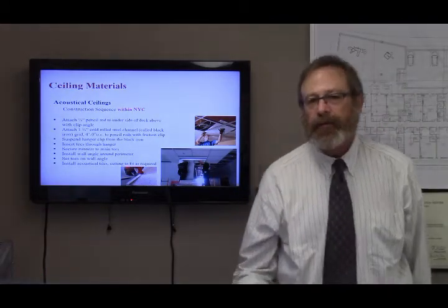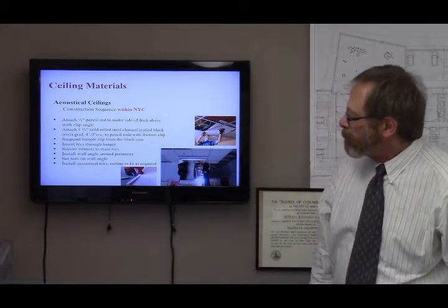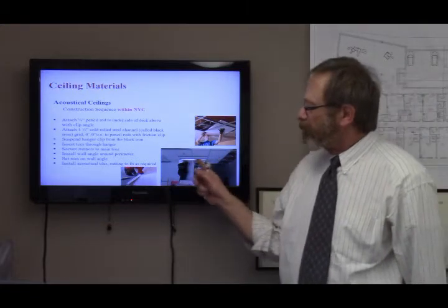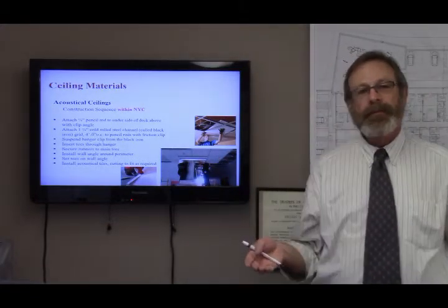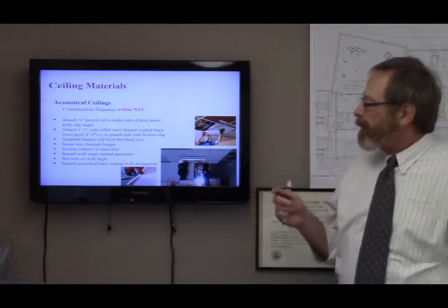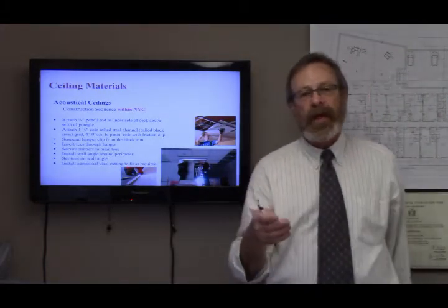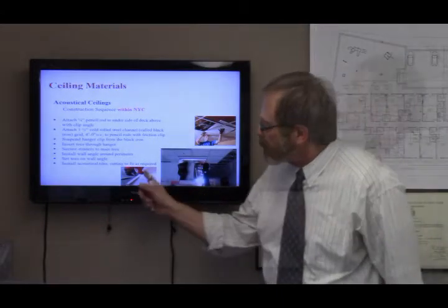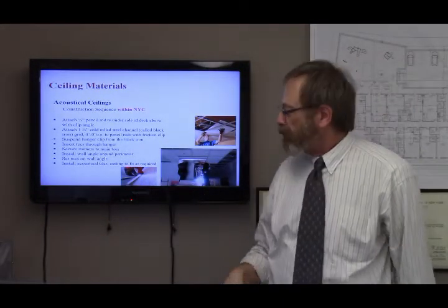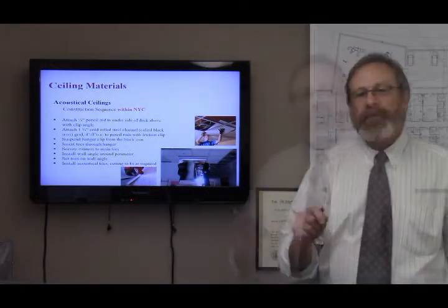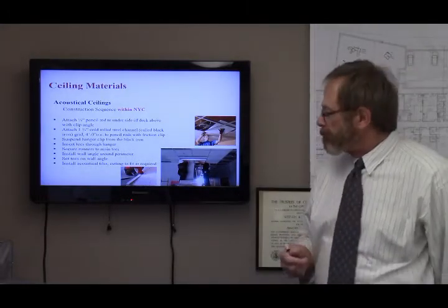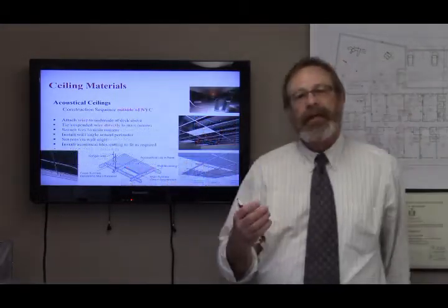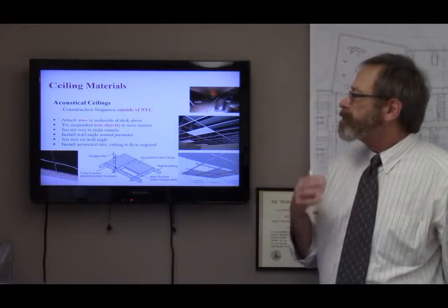Now these tiles do come 2x2 or 2x4, as do the light fixtures that we need to be able to inset into the grid, as do the ceiling registers and the ceiling supply for HVAC. Sometimes you will have to cut. They're easy to cut with a mat knife. They're only about a half inch thick and soft and lightweight. So that's how it works in New York City.